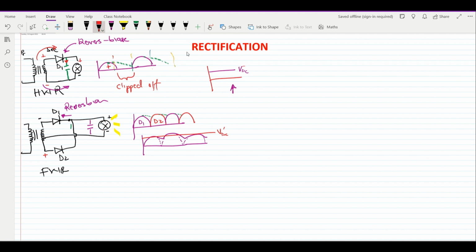Now, what is the next step that we need to employ so that we see if we can continue rectifying our circuitry? It is to introduce an inductor filter. We know that an inductor is a coil and it uses energy in the form of a magnetic field. Right? So let us go and see. We are going to use our inductor in a half-wave rectifier first. This means that we will still have our diode and our inductor, connected to our light bulb.